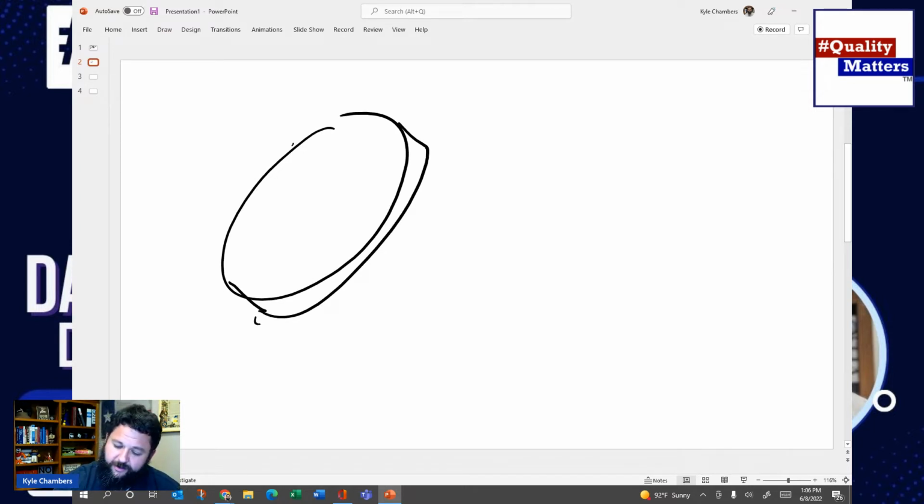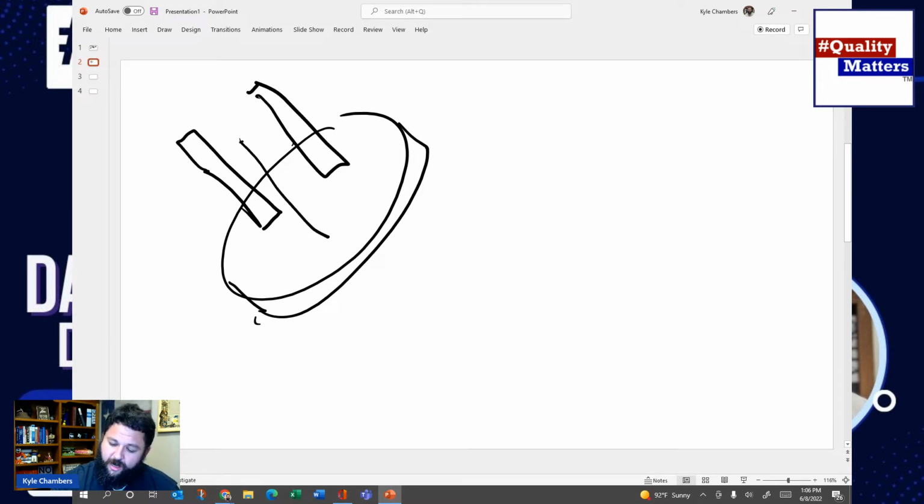And they have what we called rocket tips coming off of them. Now, obviously, I'm not making the most precise of a drawing here. On the end of the rocket tips, they had little holes, and those holes were there for the fuel. The holes had to be aligned at a certain angle, and these rocket tips were so long, that's the way we could get the proper injection into the combustion chamber.